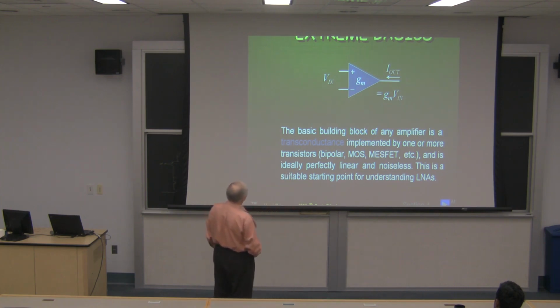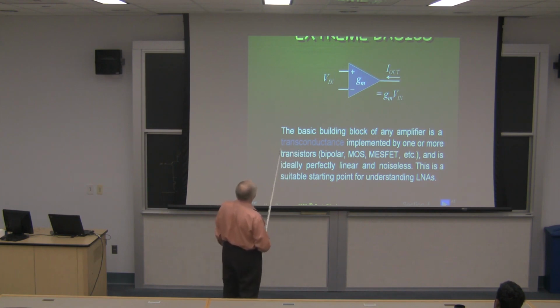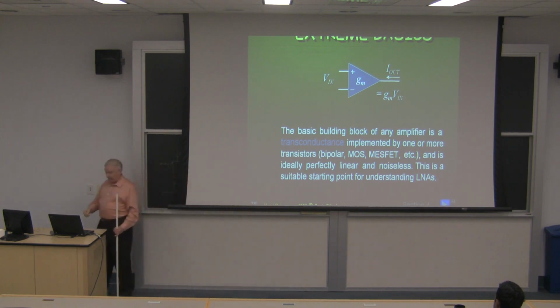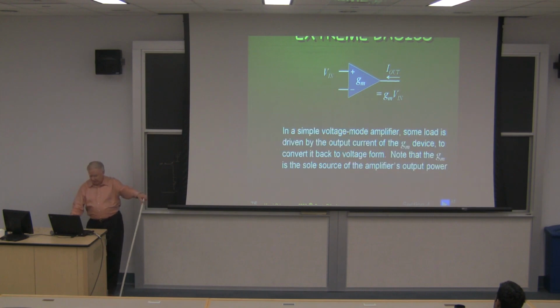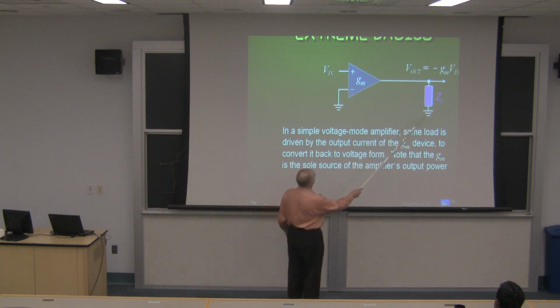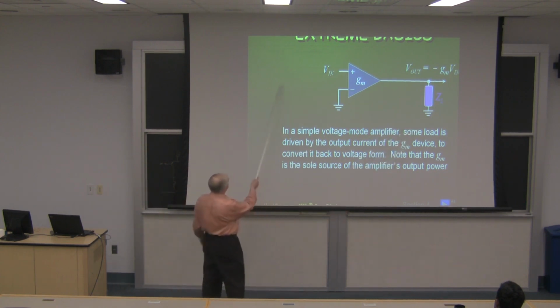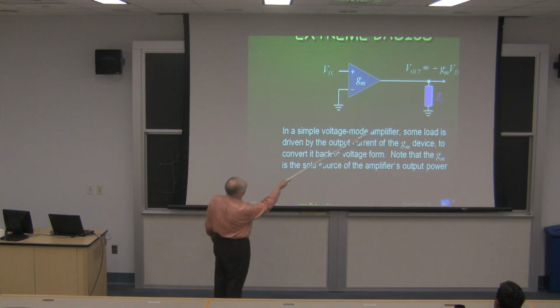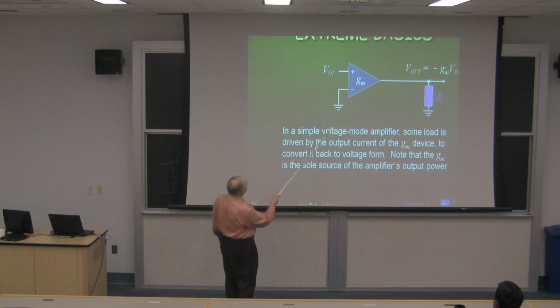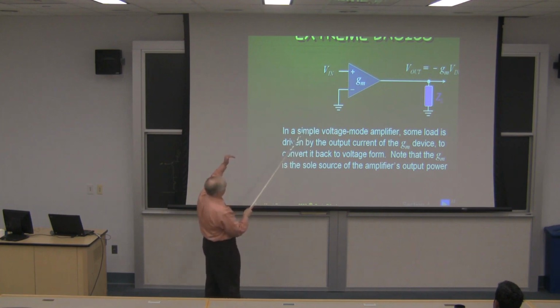And I'm not sure if I got the direction of my arrow right here, but it depends on which you call the positive and negative terminal, I guess. But the way the terminals are shown, I suppose the current will be going the other way. We'll get there, I hope. So now, let's take that GM and put it. What we're going to try to do is take a signal source of the same impedance, ZL, and arrange for this to look like ZL at the input. Let's say 50 ohms, because that's a common impedance.